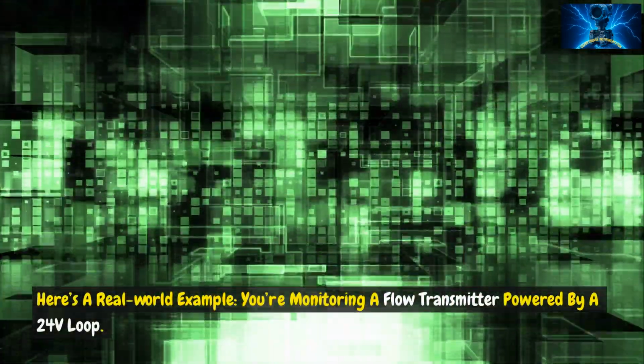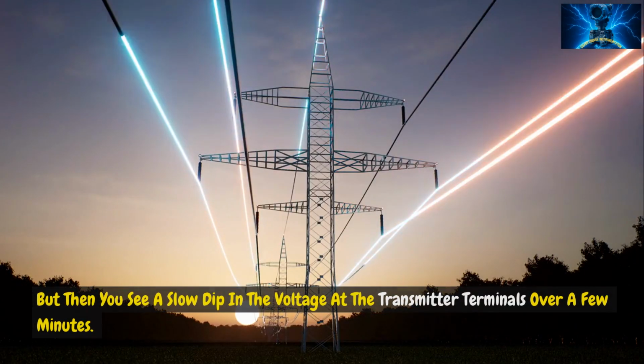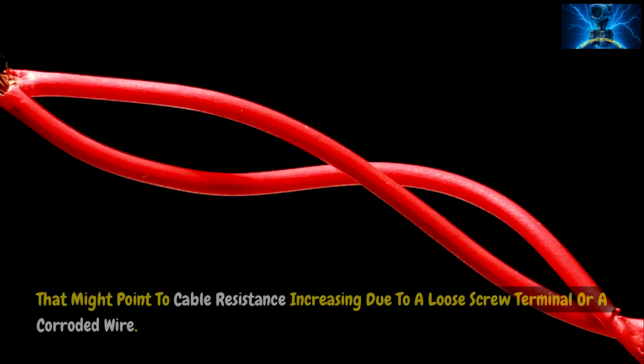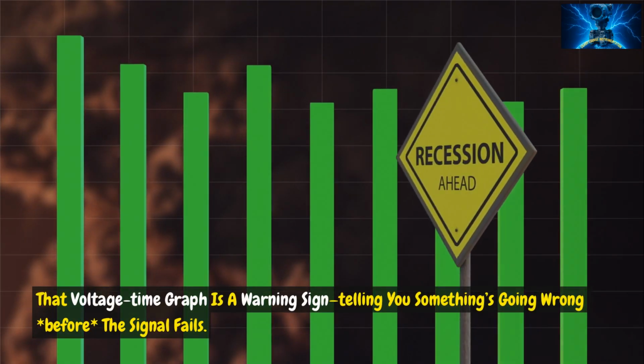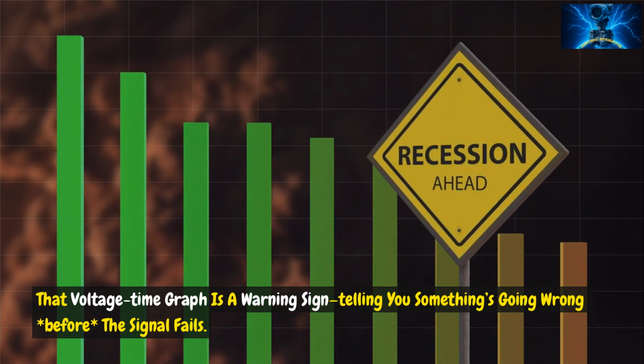Here's a real-world example. You're monitoring a flow transmitter powered by a 24V loop. Normally everything looks good. But then you see a slow dip in the voltage at the transmitter terminals over a few minutes. That might point to cable resistance increasing due to a loose screw terminal or a corroded wire. That voltage-time graph is a warning sign, telling you something's going wrong before the signal fails.